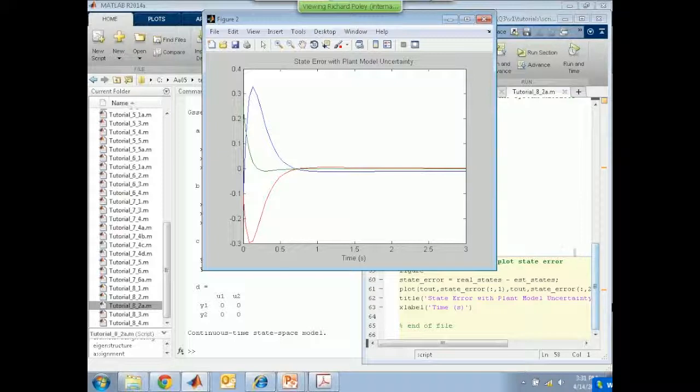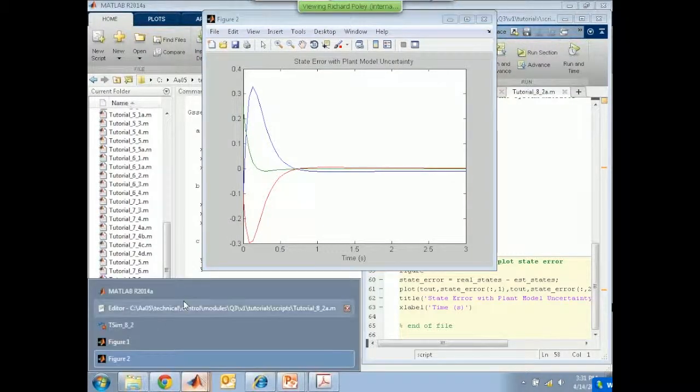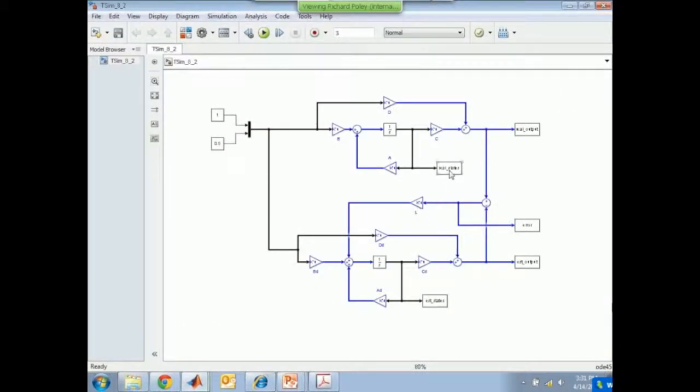I don't know how you would apply an integrator to an estimator to get rid of them. How do you know what the right values actually are? There's nothing that you can input and output of what? I mean, we don't know that we have this error. We only estimate this error based on what we think the plant states are, because I'm in a very happy situation here of having a model, right? And this model produces for me the real states.